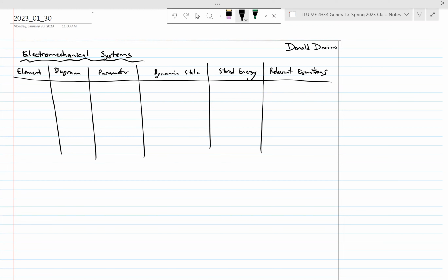So a spring, right? Or torsional spring. That's one, right? And so I will draw that either just like a regular spring, or sometimes it's a bar and I'll put like a spring constant next to it. Either one of those are okay, right? What do we think the parameter is for a torsional spring? What was it? K or KT, as I sometimes will use a subscript for that. And that is Newton meters over radians in this case, right?